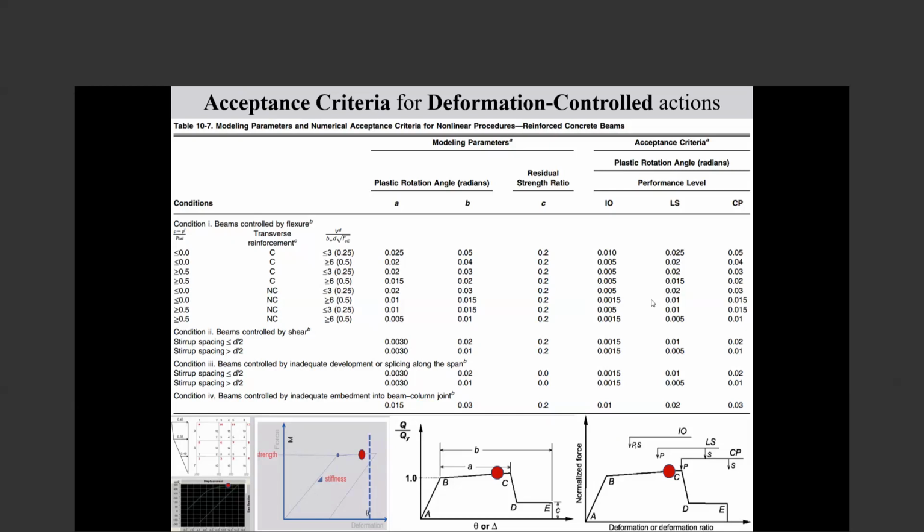So you can see from point A to B and B to C, and then the drop of stiffness. Those effects, such as strength deterioration and stiffness deterioration, those cyclic effects are seen in these curves. But any section analyzer usually gives you the response under monotonic loading.